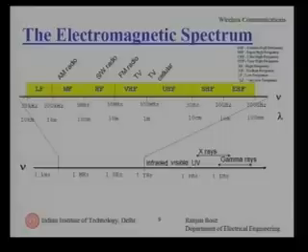Certain frequencies, for example, the 900 megahertz travels to quite a distance. Lower frequencies also travel large distances. Therefore, a TV tower and a radio tower can cover areas up to 5 or 10 kilometers, if not more. A typical 900 megahertz base station, which communicates with our mobile phones, can work easily up to 5 kilometer radius for the given power. But for the same power, if we increase the frequency, say we go to 2.4 gigahertz, the electromagnetic radiations will get attenuated much more. That is, our coverage area will get reduced.